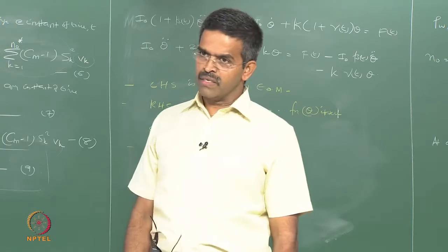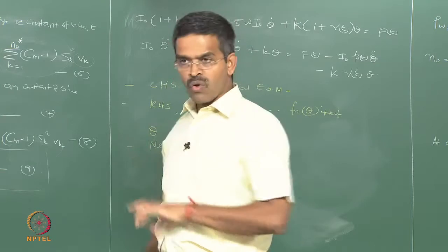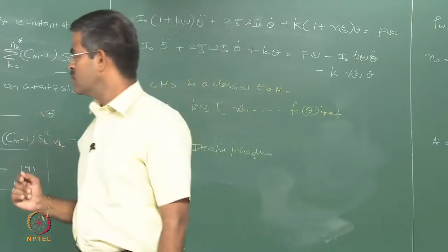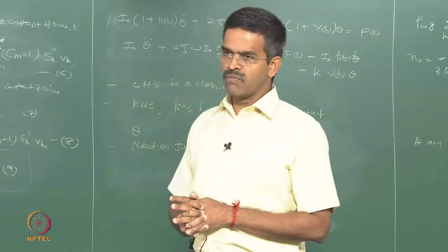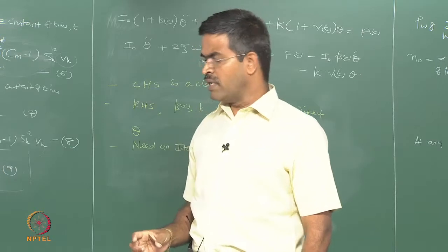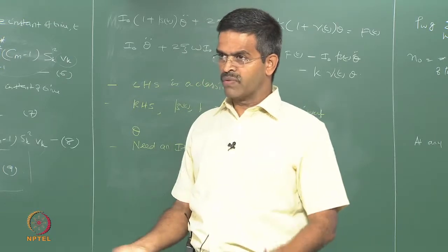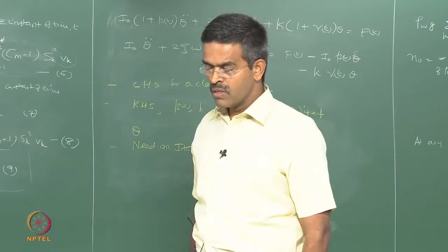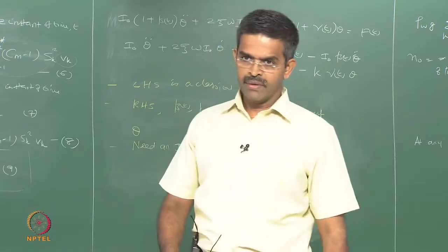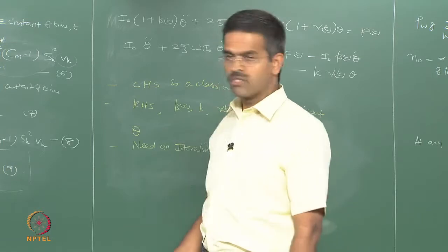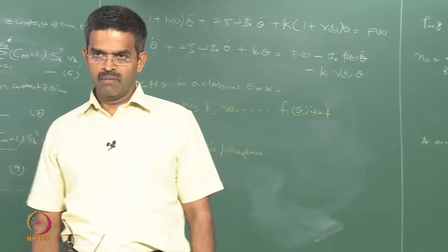Interestingly, when these towers are connected between the leg and the foundation, and the deck and the leg, with universal joints, they offer no movement to the deck, therefore the yaw motion is completely compromised. I mean, there is no yaw motion on the deck at all. Yaw motion is one of the precarious motions which is undesirable from any point of view, maybe even in a ship or a platform, because yaw motion will always cause the shift or swing of the center of gravity and buoyancy center, and that will create an additional load which will impose a moment on the system automatically. So that is not required to happen, therefore yaw motions are completely absorbed by the joints.